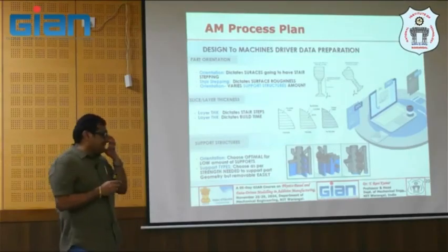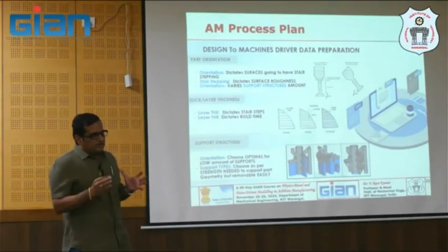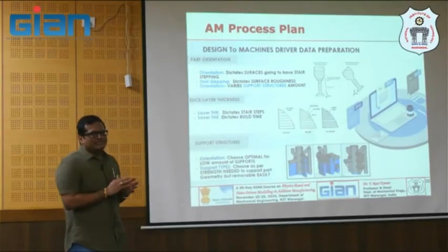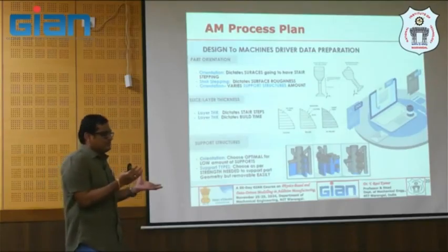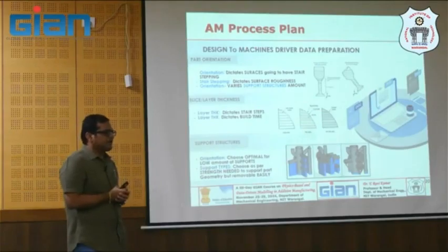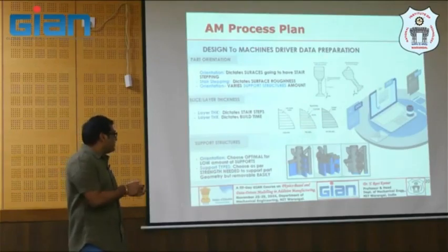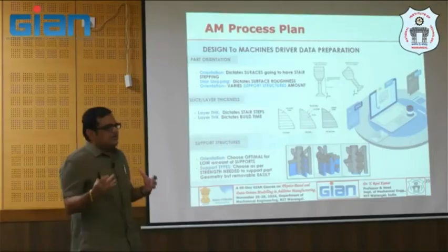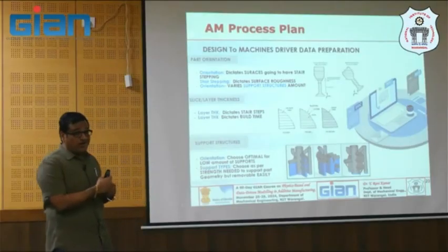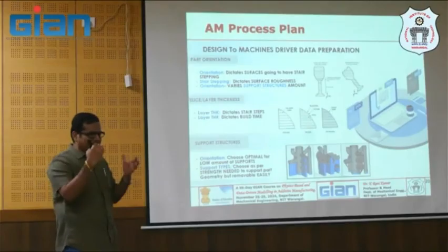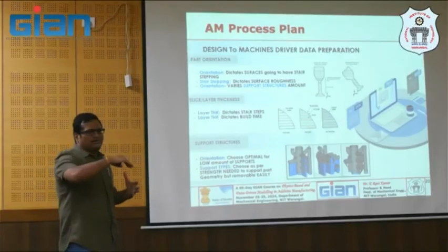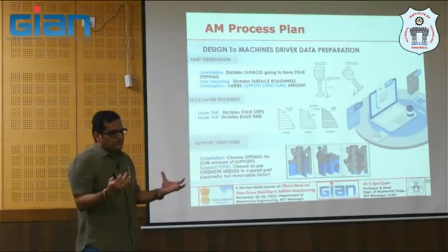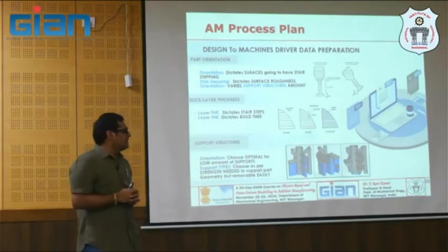Yeah, but your part orientation is going to play a major role here in order to match or leverage your properties versus your orientation. That is one of the design considerations or design guidelines. And again, you may have several criteria here, maybe a build time criterion, maybe support material minimization, or maybe accuracy, which means you want to reduce the chord height, or the staircasing effect, which may be more in one orientation than in another. You have to do a lot here in order to optimize your orientation of the part. That's going to play a major role here.